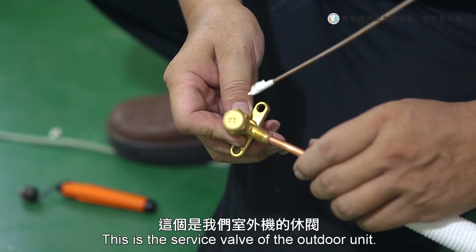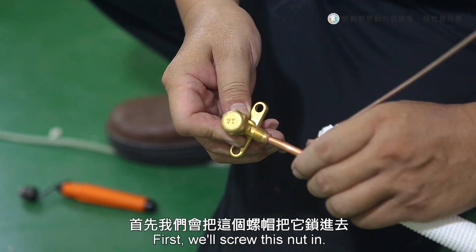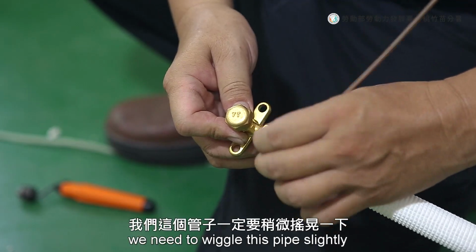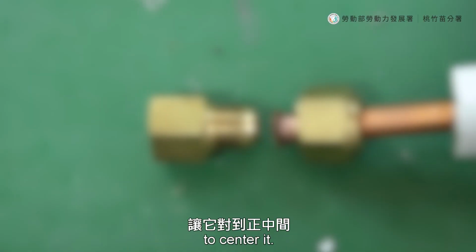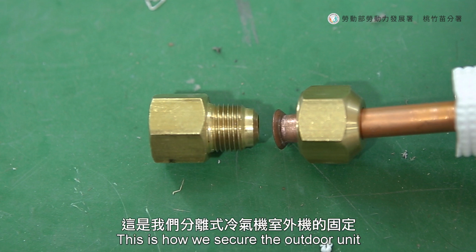This is the service valve of the outdoor unit. Let me show you how to secure it. First, we'll screw this nut in. After tightening it, we need to wiggle this pipe slightly to center it. Then we'll use a tool to tighten it further. This is how we secure the outdoor unit.